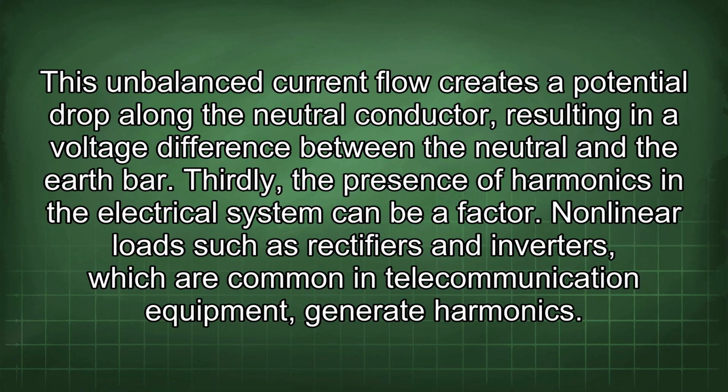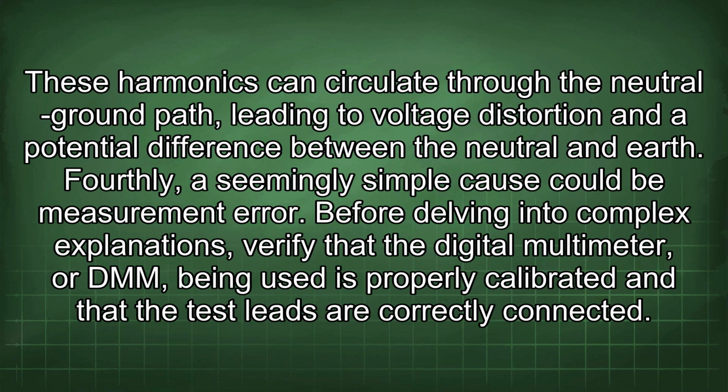Nonlinear loads such as rectifiers and inverters, which are common in telecommunication equipment, generate harmonics. These harmonics can circulate through the neutral ground path, leading to voltage distortion and a potential difference between the neutral and earth. Fourthly, a seemingly simple cause could be measurement error.